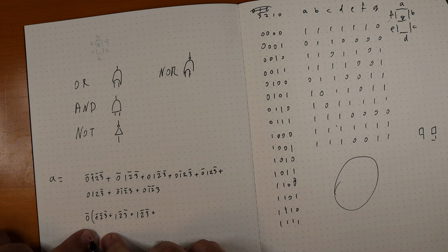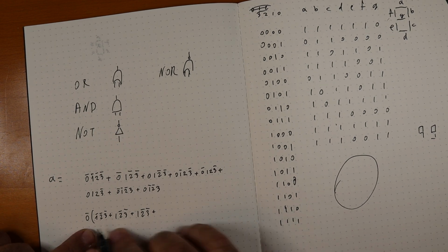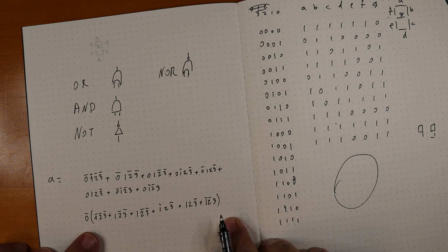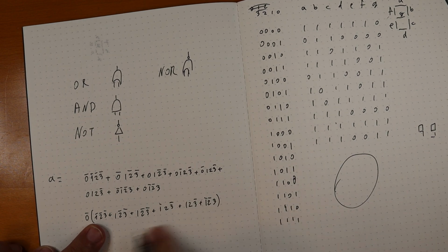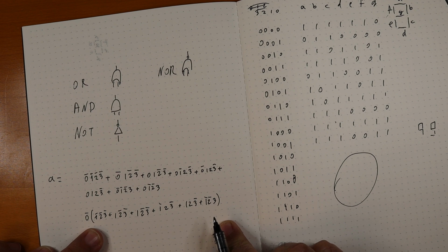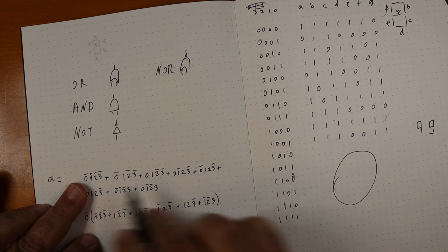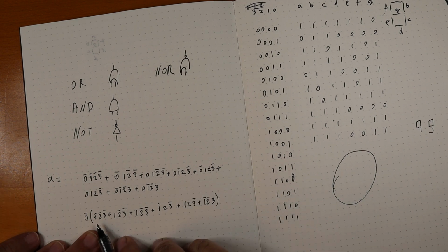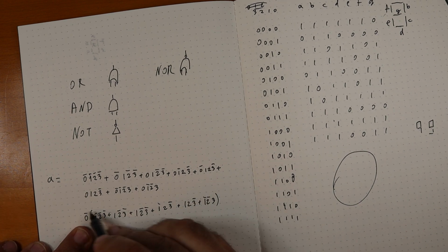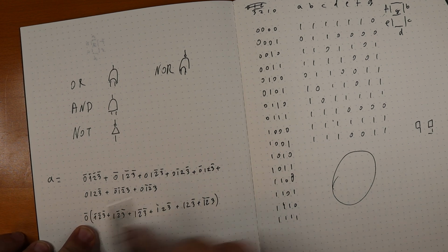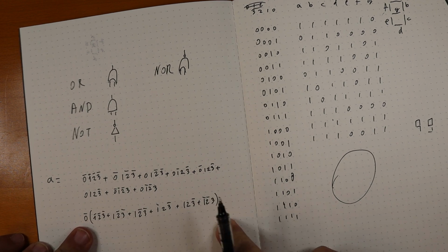And then try to get more common elements out. And that reduces the number of logic gates, because before each one of those required 3 AND gates, and now it just requires 2 and then 1 AND gate at the end. So this reduces the number of gates we need.